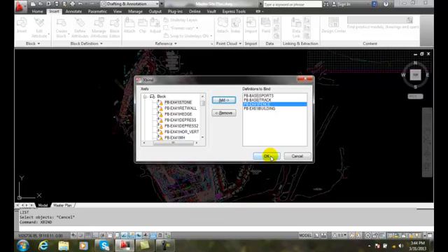So sometimes you don't need everything in your host drawing. Maybe you can just give the client certain things. When it does bring it in, it will bring in the naming standards that it does when you use the bind insert command. In other words, it will put the name of the file first, and then it'll have a $ sign, then a 0 or 1 or a number, and then another $ sign, and the name of the dependent object, like the layer name or the block name.